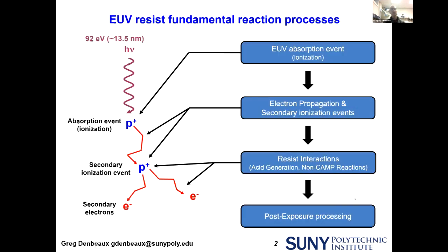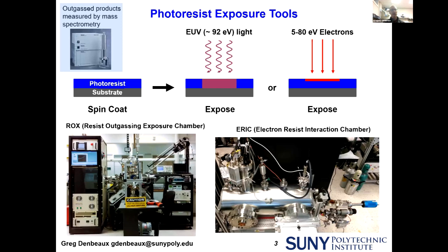And the EUV technology uses a high energy photon, short wavelength, so you can get better resolution, but that complicates the interactions of the lithography process with the materials, the photoresist used for the lithography, because the primary photon doesn't do the chemistry. The photon generates electrons, the electrons have some cascade, and the low energy electrons do the chemistry, and we're studying those interactions.